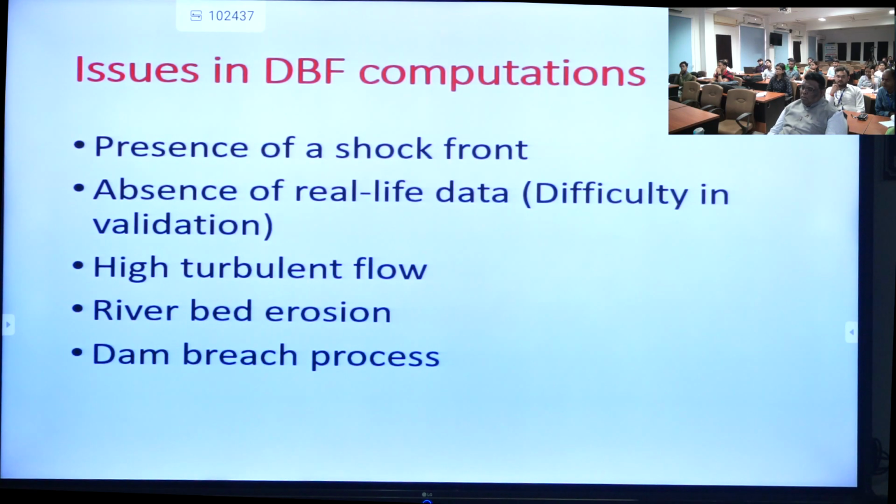And not only that, there is the presence of a shock wave. Shock wave means if you see the water surface profile, there is a discontinuity in it, like a moving hydraulic jump. So not all computer programs can capture those kinds of shocks. Okay? So these are some challenges.